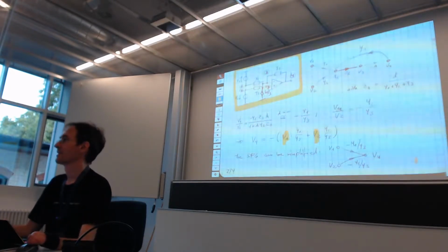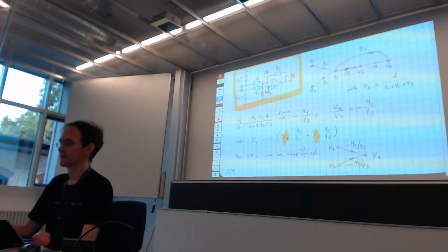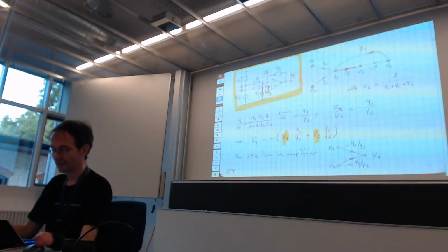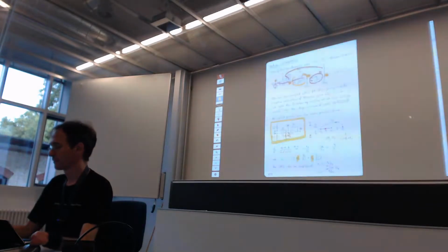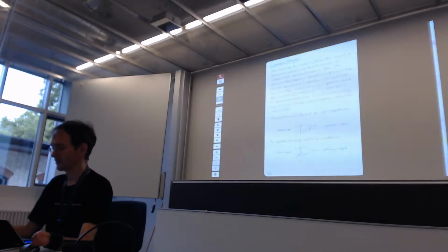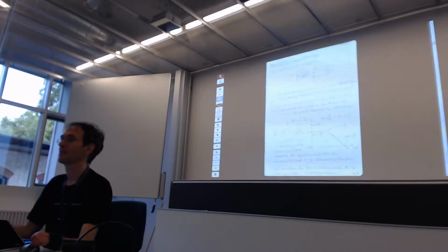It is not the same for noise, because with decorrelated noise, the different noises of the sources of the transconductors are not correlated. And then you cannot add their amplitudes. You need to add their powers, noise power.